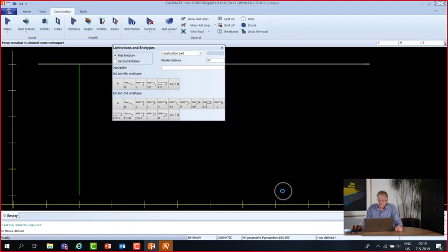I want to start from the lower deck with a small gap of 40 millimeters, and then an important part is coming. You see here all the end types, all different kinds of end types, whatever you call them. But I prefer to use the auto button. The auto button takes care that the right end type is chosen all the time, based on the customer's situation.